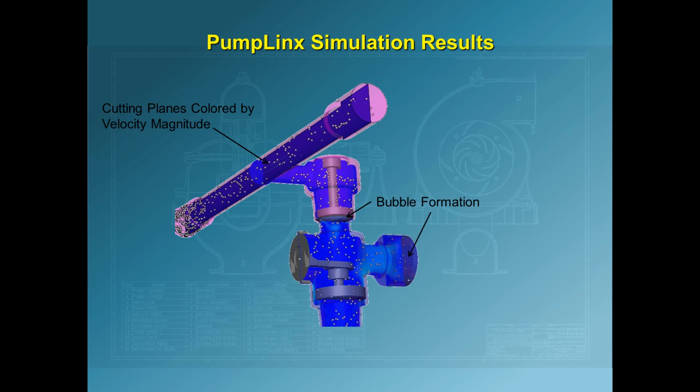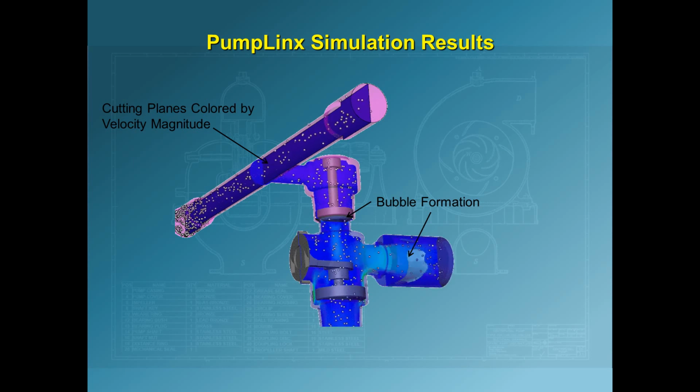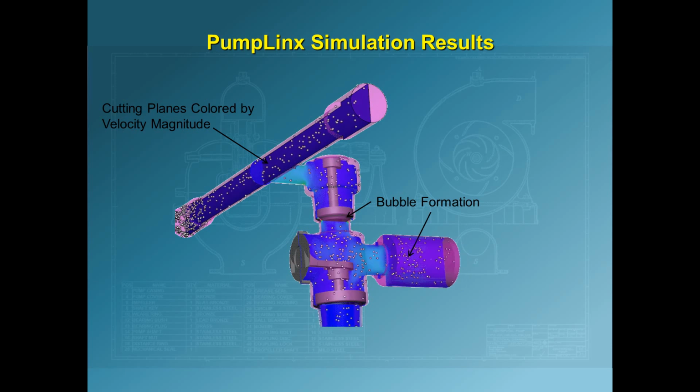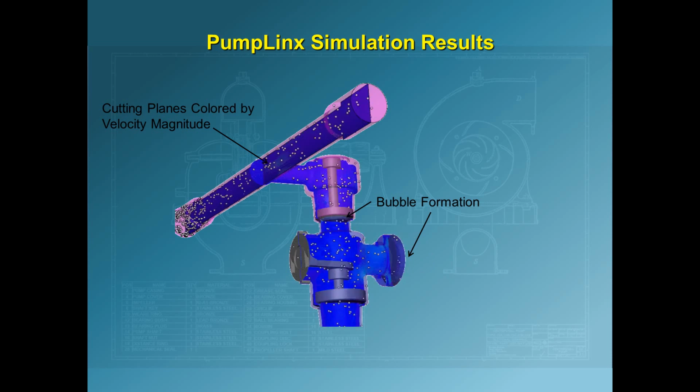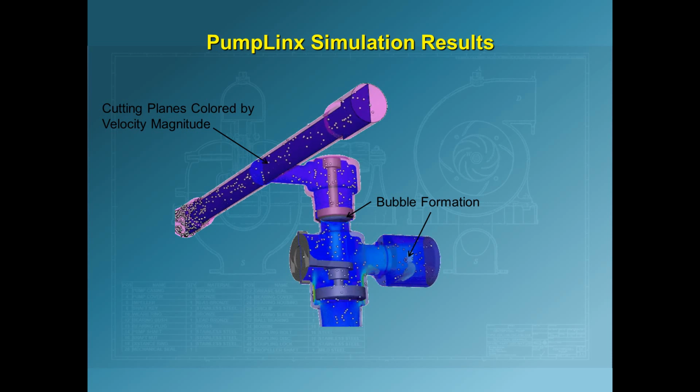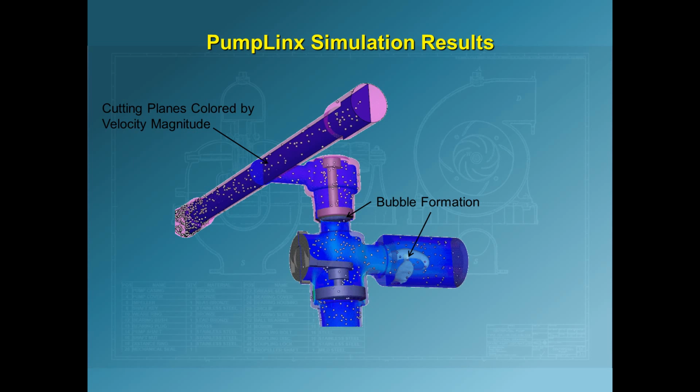Bubbles are formed in the piston chamber and under the valve outlet due to the pressure drop during the expansion stroke as the fluid opens the inlet valve at the bottom. During the compression stroke, the inlet valve closes and the outlet valve is forced open by the fluid pressure.